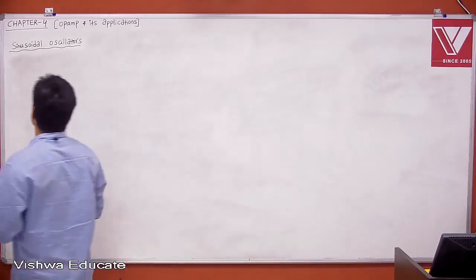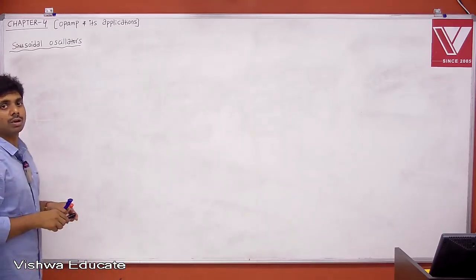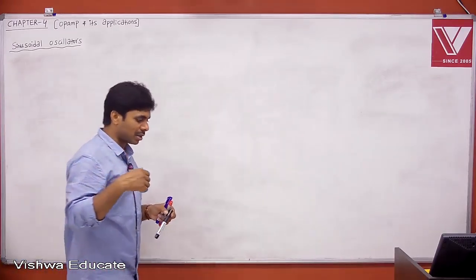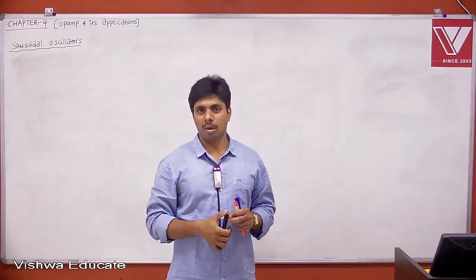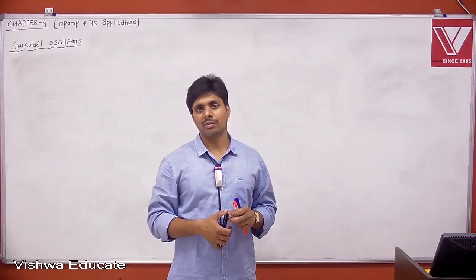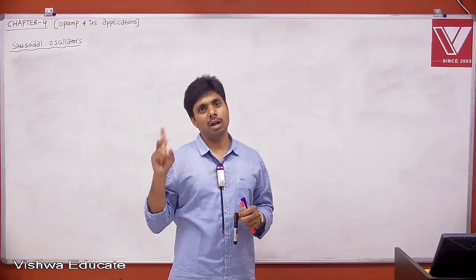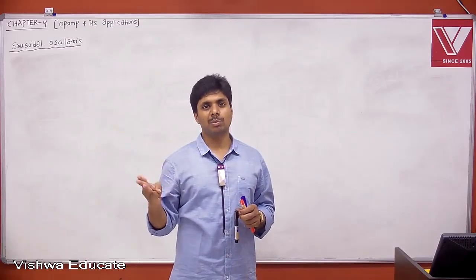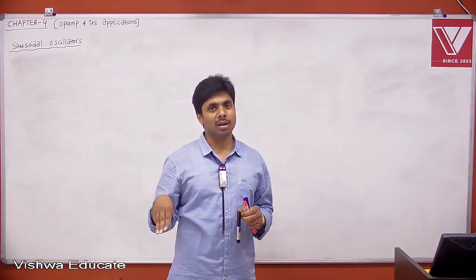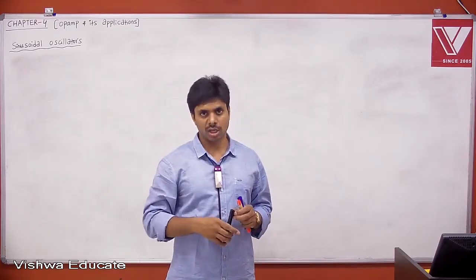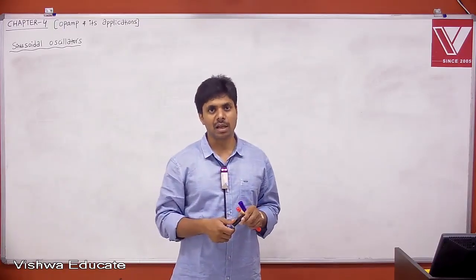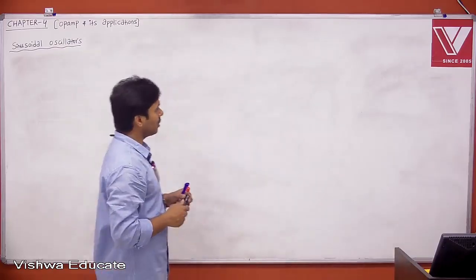Now, I just explained before using root locus, one pole system, because I explained that with respect to Opamp, right? Because we did Opamp compensation to get stability, and we know that one pole system is always stable, two pole system is always stable, three pole system may be stable, may not be stable, four pole system may be stable, may not be stable. That depends on the K variation, right? Which is nothing but DC gain or low frequency gain, whatever it may be.